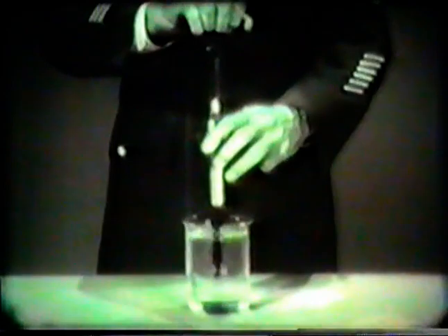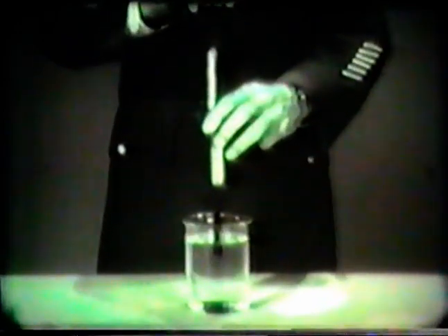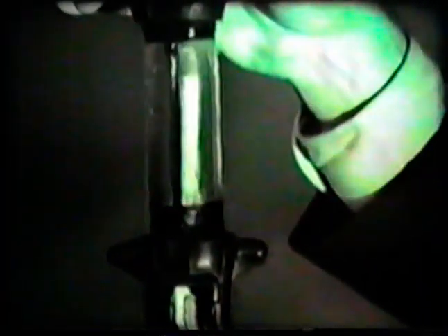To use a hydrometer, the bulb is squeezed and electrolyte is drawn through the flexible tubing into the glass tube so that the float is immersed in the electrolyte. The hydrometer is held with the tube vertical, and the depth to which the weighted float sinks in the electrolyte is read on the graduated scale.